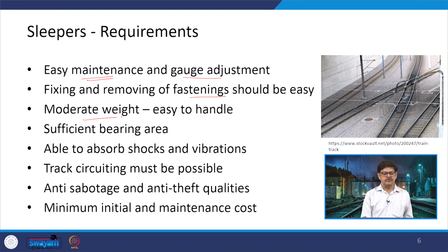These sleepers should not be very heavy, but at the same time they should not be too light. So, there should be a moderate weight, and this moderate weight also has to be looked at in the sense that they should be easy to handle. It should not be a requirement that we need very heavy machinery at the location where the construction or the renewal is going on, to lift the sleepers.